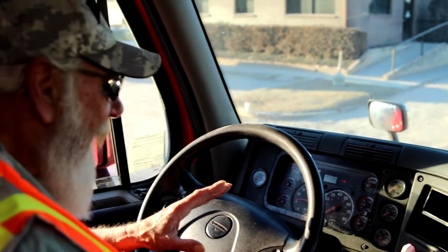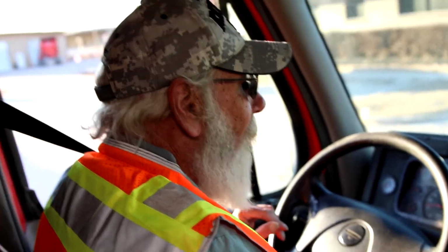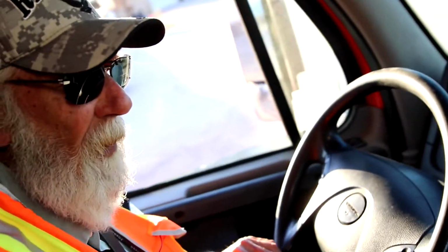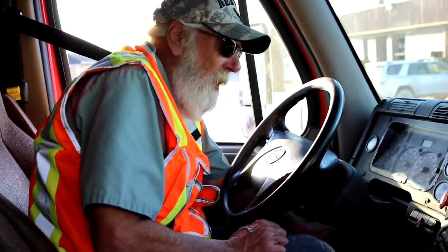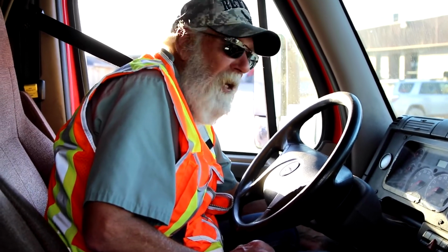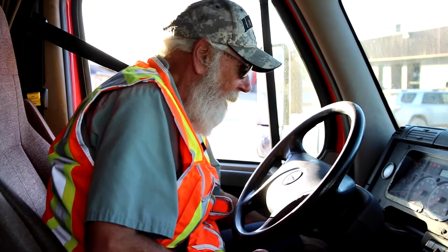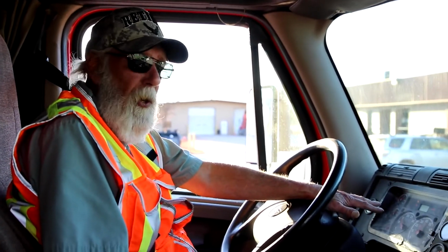Make sure that you have plenty of air pressure to conduct your brake test. So when you are ready, place your truck in first gear, turn the engine off, step away from the clutch, turn the electrics back on, where all the warning lights and your gauges should make their sweep.